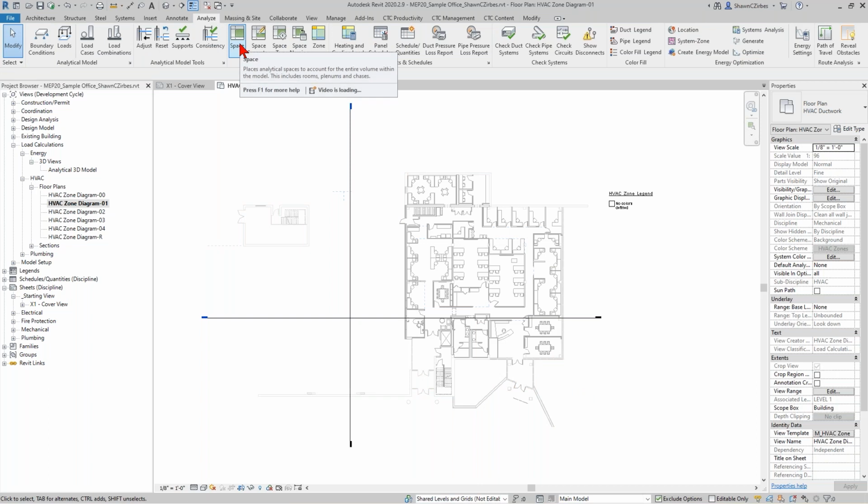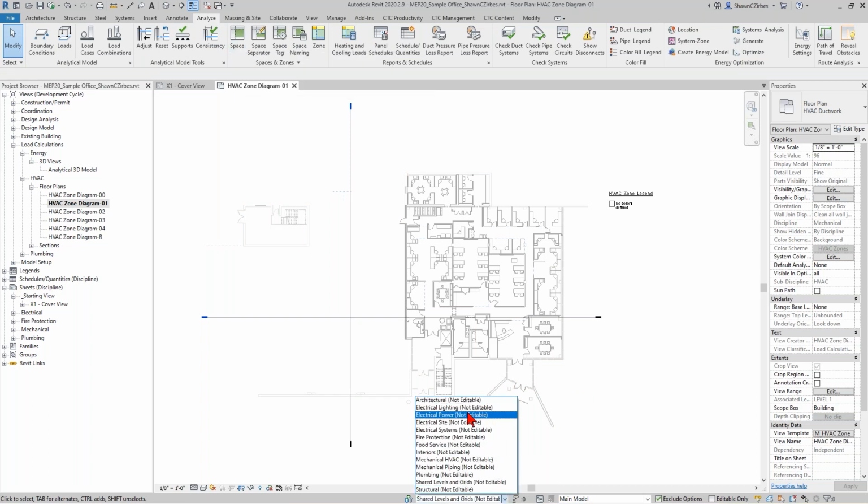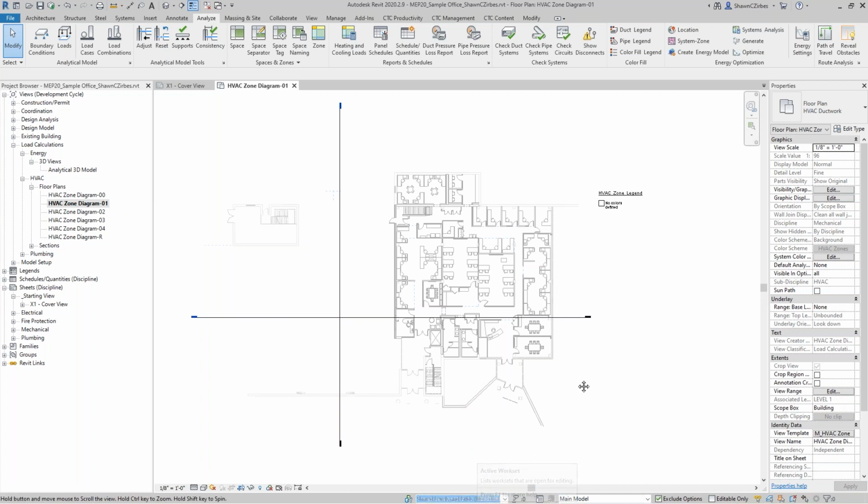of your space elements. Now, when you go in to drop in your space elements, you may want to just double check and make sure you're on a good work set for this. In this case, my spaces I tend to put on the shared levels and grids work set here because it goes beyond just mechanical HVAC, right? This affects all of the disciplines. It's useful across the board. So I'm just going to stay here on shared levels and grids for right now at this point.